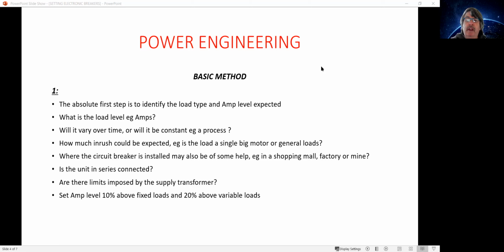They don't generally impact the breaker because they're little motors maybe, and that type of thing. It could also be things on a factory level or a mine. It might be one mine super motor, a 200 kilowatt motor fitted on some ACB, in which case every time that starts, it goes through a cycle of an inrush.